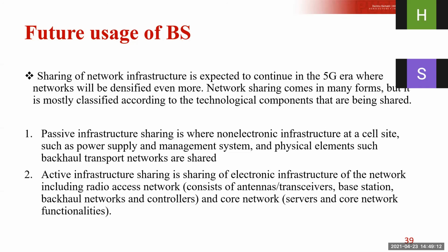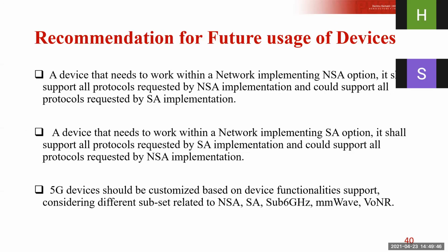So what would be the future use of base stations? It will be sharing infrastructure that will continue for those base stations, whether 3G, 4G or 5G. And there will be passive infrastructure and active infrastructure. By passive infrastructure, I mean the non-electrical infrastructure at a site, like power supply, management system, and physical elements. By active infrastructure, I mean electronic infrastructure, such as antennas, transceivers, base stations, backhaul network, and so on.